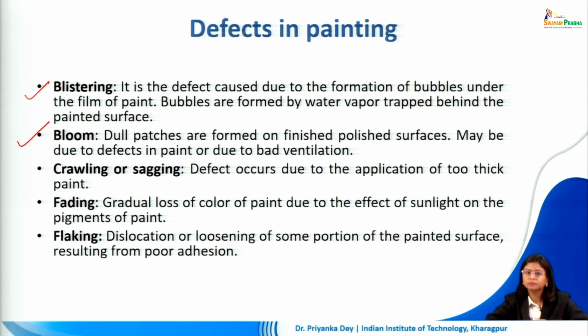Bloom. These are dull patches which are formed on the finished polished surface. This may be due to defects in the paint, or it may also occur if there is bad ventilation in the space that we are painting.